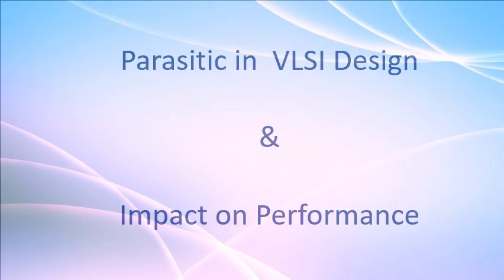In very large-scale integration design, parasitics refer to unintended and unavoidable electrical elements that arise from the physical properties of materials, geometrical layout and device structures used in semiconductor fabrication. Although they are not deliberately designed into the circuit, parasitics significantly affect the performance, speed, power consumption and signal integrity of integrated circuits. As device dimensions continue to shrink into the nanometer scale, the impact of these parasitic effects becomes more pronounced, often dominating the ideal circuit behavior.